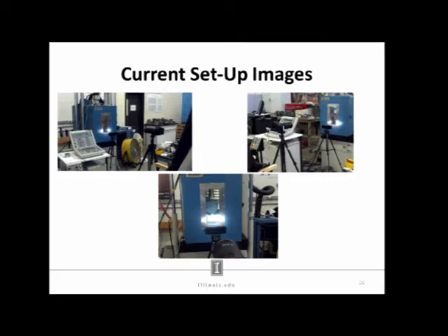Obviously, if you do have an angle there, you may not be able to tell it, but you're going to be able to see differences in your deformations if you ran more than 3 to 4 specimens and you saw a drastic difference between them. You can easily use stereoscopic digital image correlation. That's something that we're probably going to move towards in the future, but right now we're focusing on a single plane rather than looking at it from an angle, which is the easiest way of applying digital image correlation.